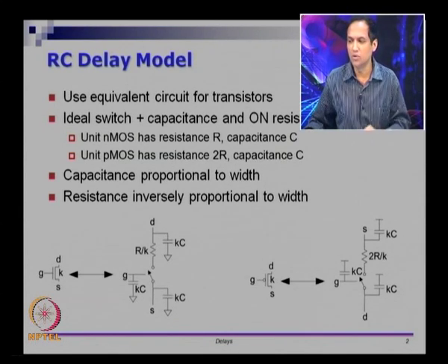calculation. What we are going to do is assume that there is this NMOS device here, and I already mentioned in the previous video that there are various kinds of capacitances: gate to drain, gate to source, and gate to substrate. Let us say I add all of them and put them as one capacitance here. So let us not worry about these quantities here. G is gate, D and S are drain and source, and if I have an inverter, then I am going to have an NMOS device. So I am taking one particular NMOS device.